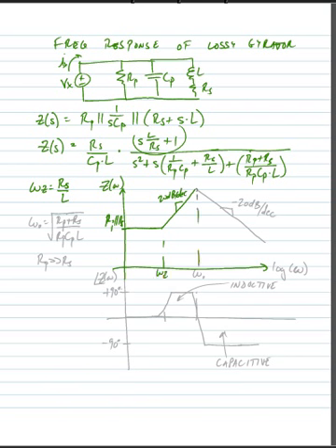At a resonant frequency, which would be equal to the square root of RP plus RS over RP CP L, assuming that RP is much, much larger than RS, at our resonant frequency we would get 2 poles that would cause a roll-off of minus 20 dBs per decade. And of course, this is plotted on a log of omega scale.